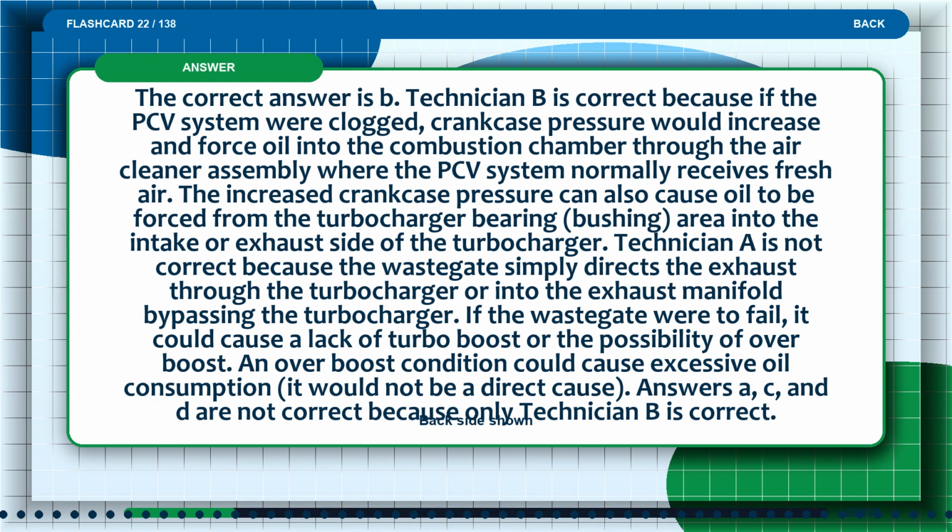The correct answer is B. Technician B is correct because if the PCV system were clogged, crankcase pressure would increase and force oil into the combustion chamber through the air cleaner assembly, where the PCV system normally receives fresh air. The increased crankcase pressure can also cause oil to be forced from the turbocharger bearing bushing area into the intake or exhaust side of the turbocharger.